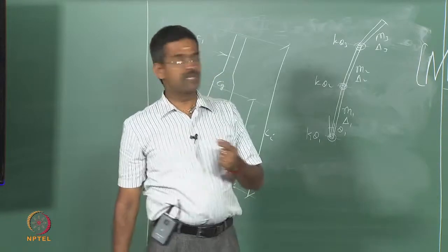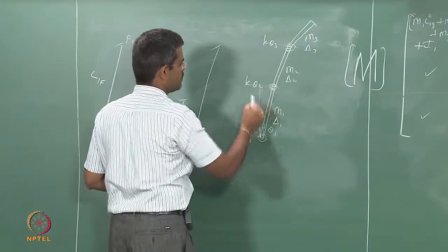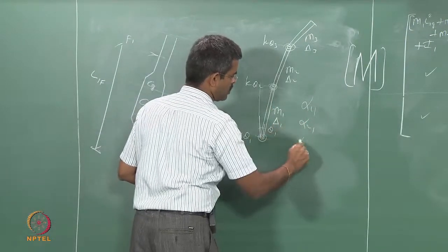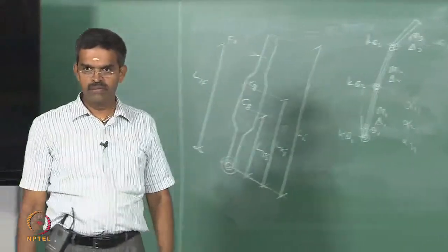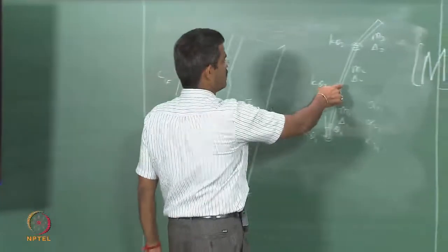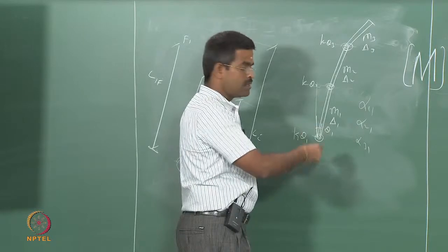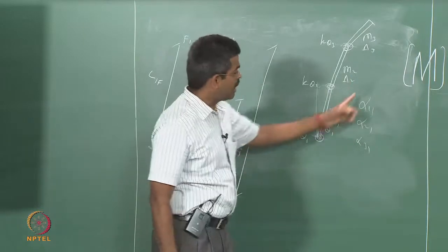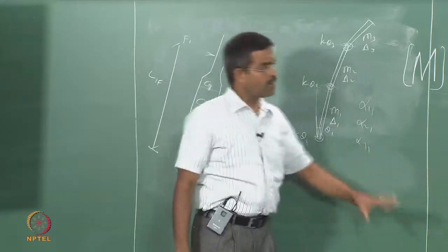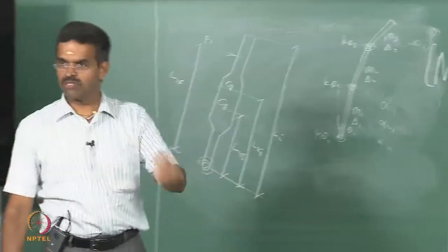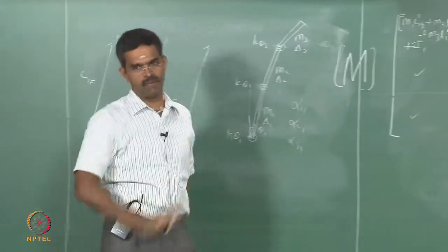I will give you a very simple method to derive the stiffness matrix. Give unit displacement here, get alpha 1 1, 2 1 and 3 1, and invert it to get k. I mean, give unit displacement here and try to find the influence coefficients in the earlier manner that we explained. You will get the alpha matrix, which is 3 by 3, invert that, you will get a k matrix, which I am not writing it here. There are papers which I will refer back in the presentation. You can see that you will exactly have the same mass matrix and same k matrix available in the paper.